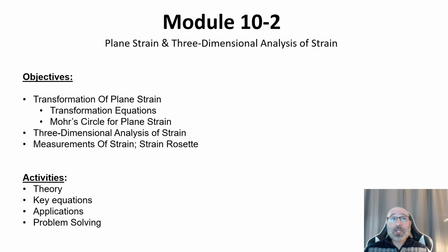For Module 10.2, we're going to take a look at our plane stress and our three-dimensional analysis of strain. The objectives within this module: we're going to take a look at the transformations of our plane stress, looking at our transformation equations and Mohr's circle for plane stress. Then we'll get into our 3D cases for the analysis of strain and talk about the measurements of strains and get into the strain rosette as well.